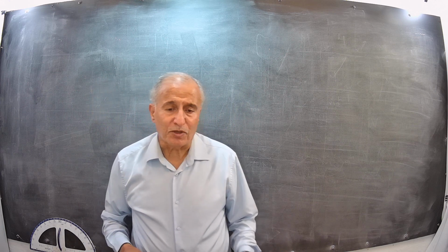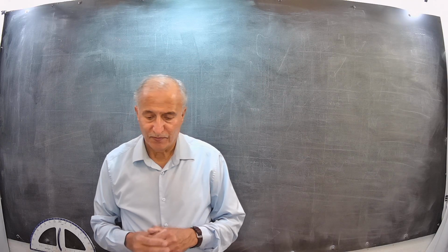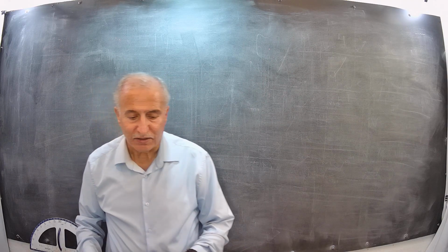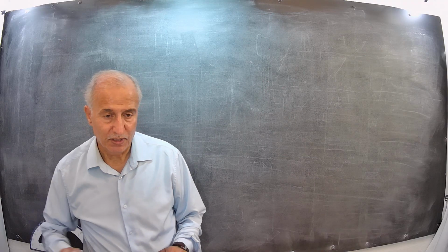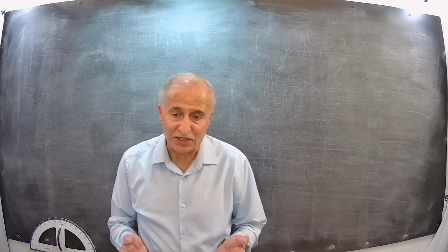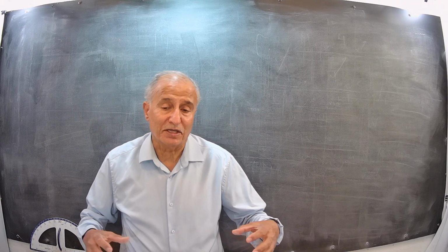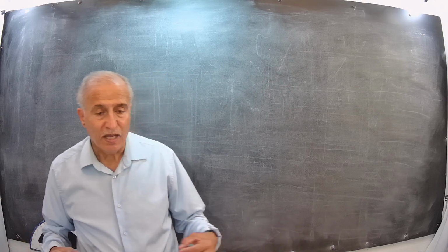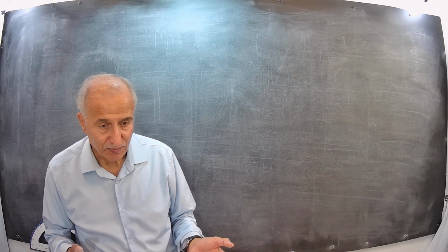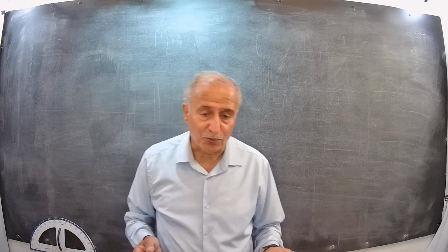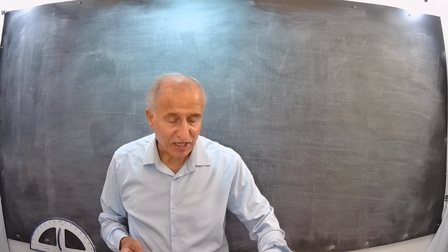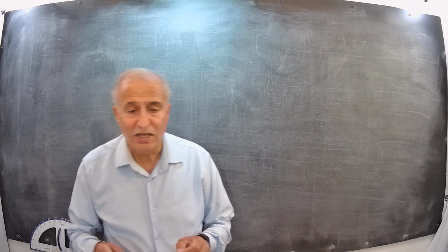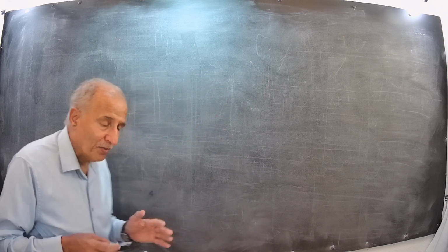A student asked me about the castellated beam, and this is the method that engineers use to increase the load carrying capacity of a beam. Castellated means the beam has hexagonal openings, or a cellular beam, which has circular openings. I explain this increase in load carrying capacity with a simple example, step by step.